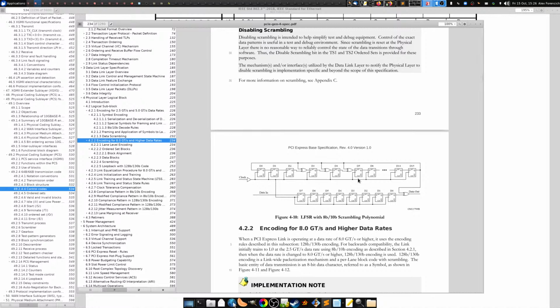With Ethernet, the devices could be on opposite sides of the country, and you can't afford to do this kind of scrambler synchronization, because you don't necessarily have a bidirectional link, or you could have a very high delay. So everything is set up in Ethernet to loosely couple the transmitter and the receiver.